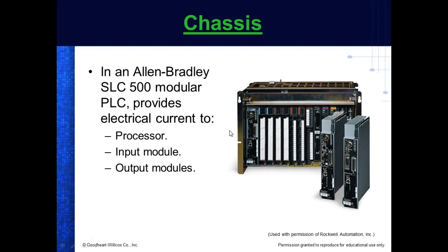So this is the modular PLC. So you can get different communications. This comes with a data highway. It also comes with RS-485, which is, if you ever seen a computer, so RS-232 is the same thing. And that's the only two here. But if I wanted to have Ethernet IP or Ethernet, then what could I do on this? I could buy a communication module. No, I could probably buy a communication module and go ahead and do that.